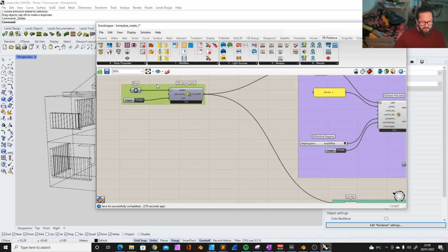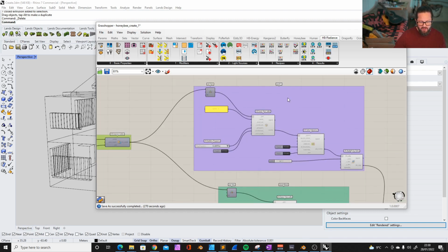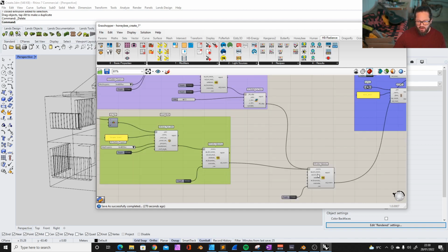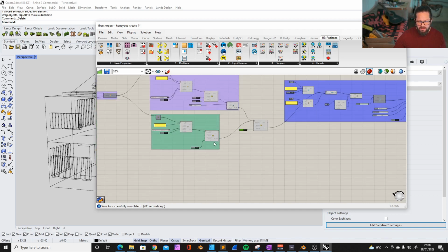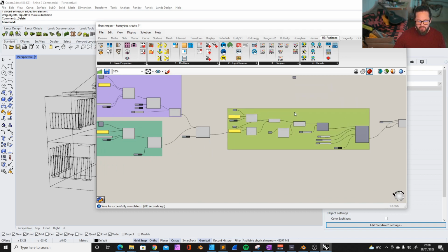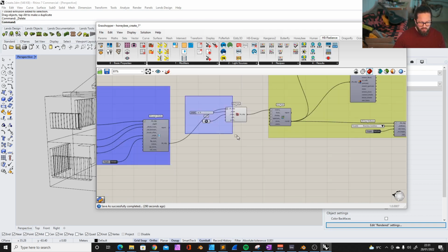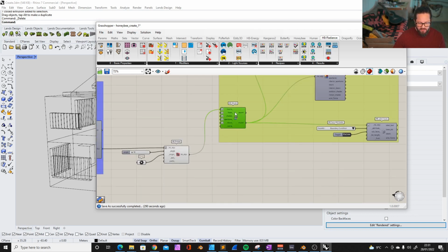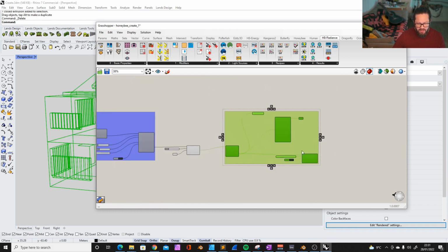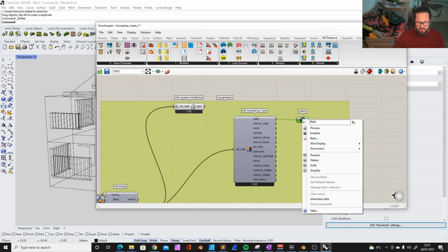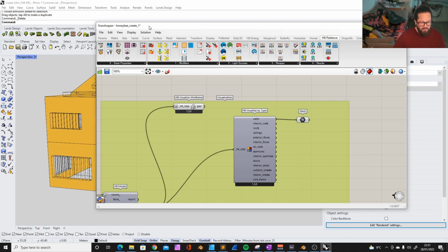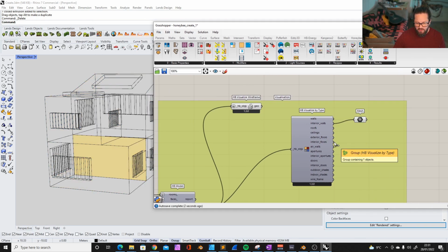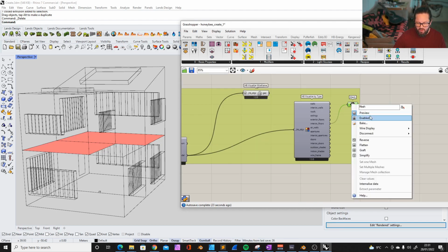So, okay, here we just prepare basically the geometry. We set up these rooms. We solved all the adjacencies, as you can remember. Then we applied apertures. And then we also showed how you can modify or rotate your model and so on. And then we put everything in a Honeybee model and visualized it based on what we want to see. For example, we wanted to see the exterior walls, interior floors, and so on. And for now, I just turn this off.